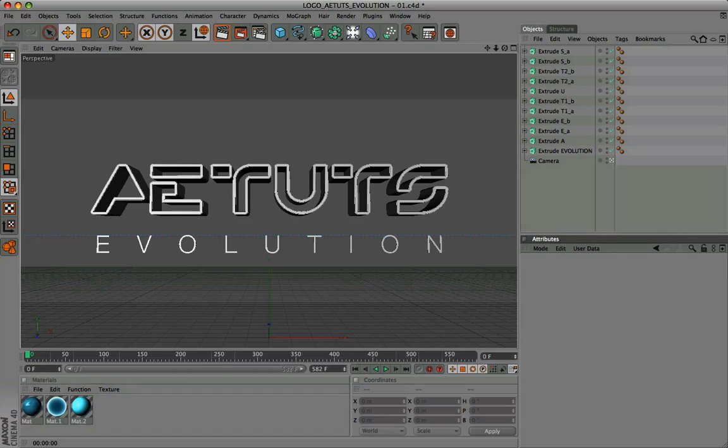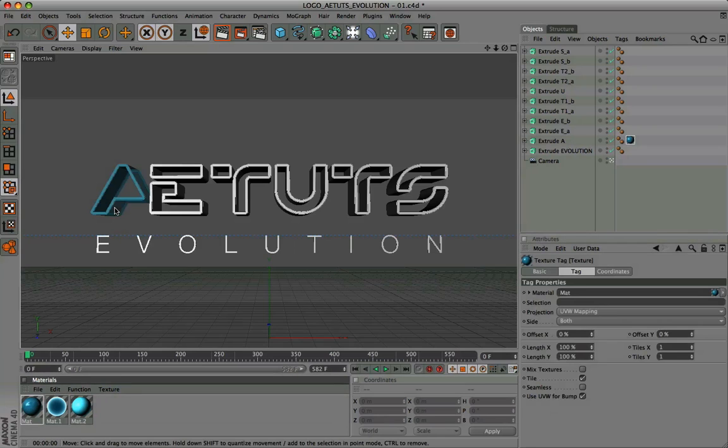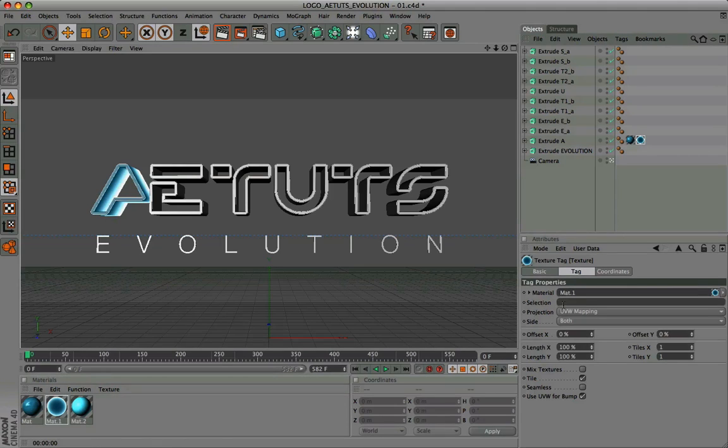Once we have created the three materials, we can apply these to the extrusion of all the letters and parts of letters. Again, we apply one, then repeat the operation on all the other extruded letters. Then insert the first material on the A letter. Immediately after, drag the second material, always on the same letter. Selecting the second material, on the selection line write C1, so the second material will be added only in the front caps.